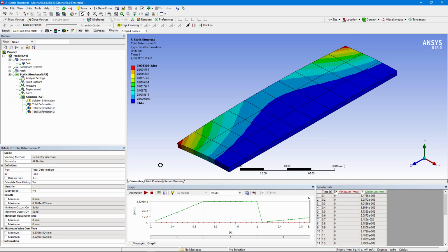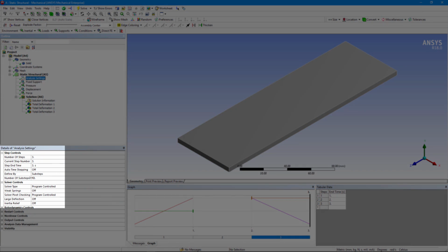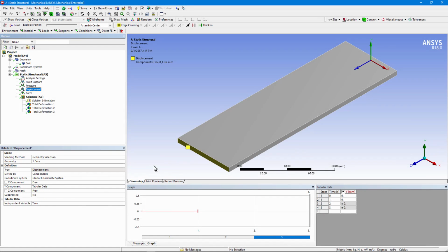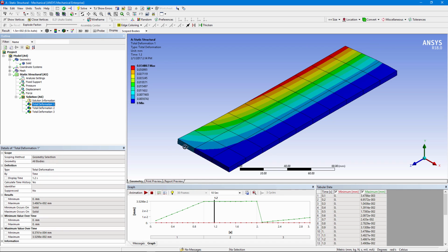Users can take advantage of this, but they also have to be very aware that a specified displacement that could be 0 or non-zero can be deactivated. But in the load step where it's first deactivated, if you are taking substeps, such as I've taken here, I've taken 10 substeps in every load step, then although the displacement constraint is turned off, reaction forces exist until the end of the load step, and you'll get this gradual release of what's happening on the left edge.